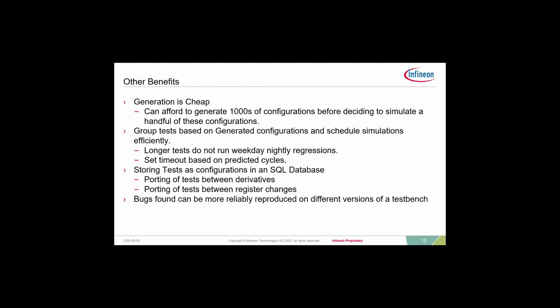You can run them on weekends, or you can set simulation timeouts based on how long you predict these tests to run. And storing your tests is also very useful, makes them very easy to search if you put them in an SQL database like we do. And you can write scripts to port tests to newer versions of your IP, or if there is a change to the register specification, you can port these tests as well, and they become very good starting tests for the next generation of your IPs.